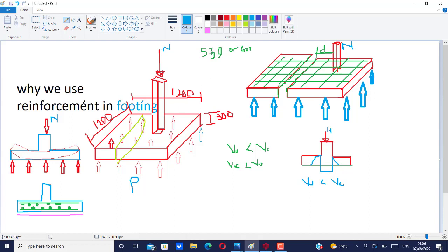You know that you want to check, because there are three things that can happen to this footing, and you want to check for one-way shear. You check for the one-way shear to know whether to provide shear reinforcement or probably also increase the thickness of your footing to make sure that a situation like this doesn't happen. Then three, you need to also check VC. The reason we are using ultimate V is because by then we have loaded the structure.